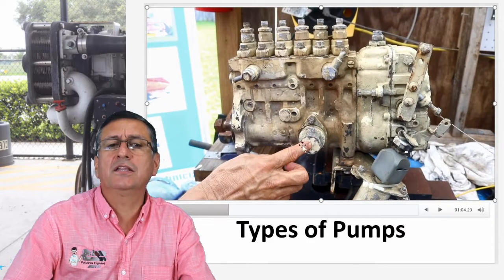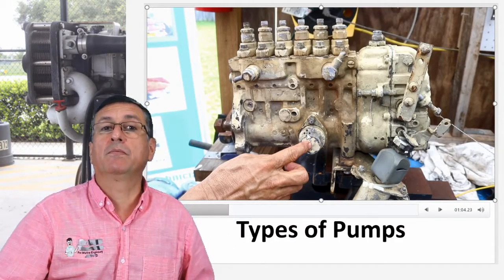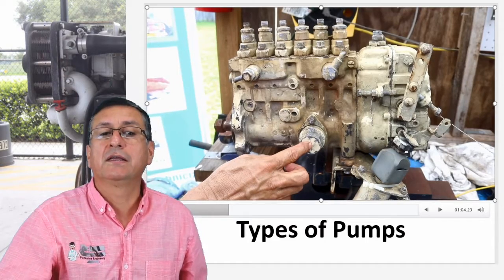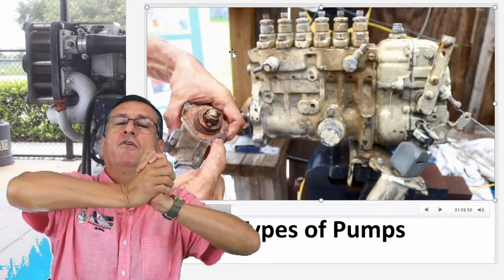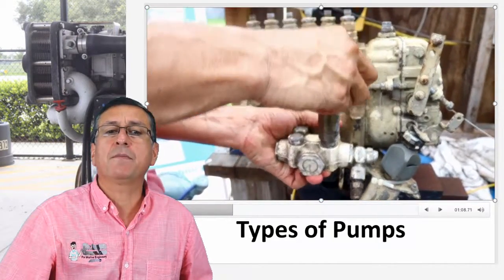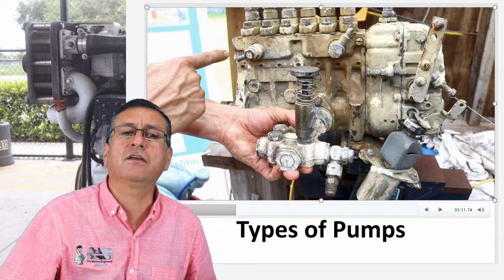Okay, normally in this position is located the priming pump, the manual, mechanical priming pump. That priming pump is moved by the small camshaft of the fuel injection pump. This one, exactly, that pump. This is the mechanism that is compressed by the camshaft of this small mini engine. Yeah, and it's bolted over there, and you can prime with your hand. This is the handle.